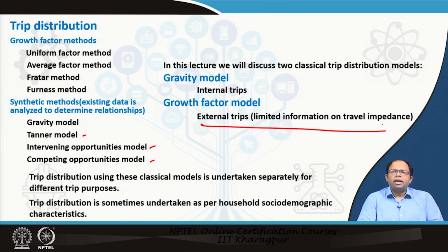So, if I have done it just based on trip purpose, then I would not be able to say how many of these people who are traveling from I to J for trip purpose work belong to which socioeconomic group. That is why, if I have divided the data previously into different socioeconomic groups, and based on different trip purposes we have done the distribution, probably we will end up with overall trip matrices, OD matrices we call them, in such a way that could be used in a mode choice model which can utilize this socioeconomic data set.